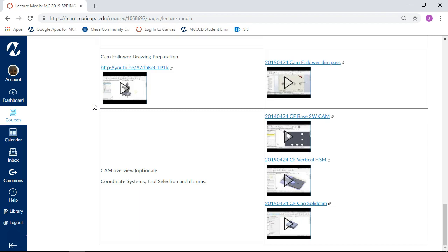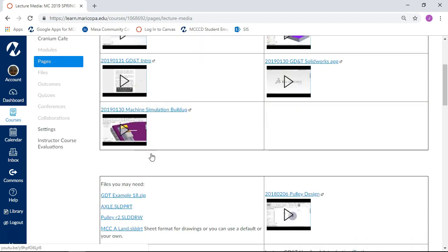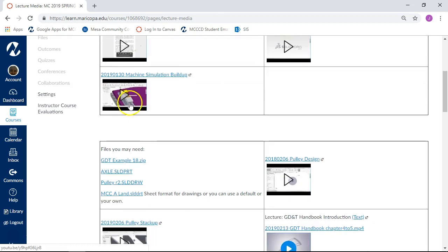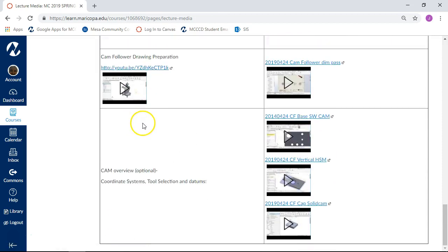And it goes back to the very beginning where we did that quick stack up on the machine simulation, where it had the table and then a subplate, and how parallelism affects the vise, and the stack ups, and then the parallels actually going into the vise, and then finally we would have put a part. Each one of those elements is something that can affect our tolerances.